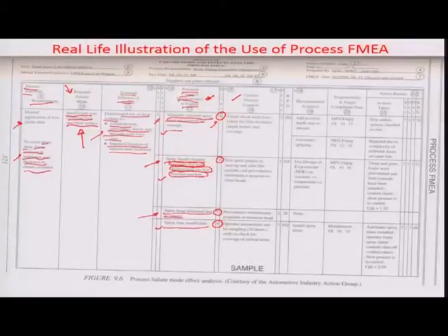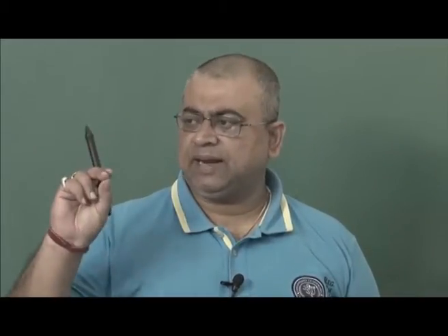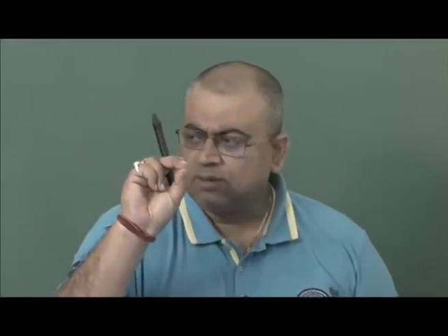For example, for the manually inserted spray head not inserted far enough mechanism of failure, he finds that the process control is to visually check each hour, maybe one vehicle per shift, for film thickness. This can be done using a depth meter, where the insertion into the wax layer might give a marking on the scale through which you could measure the thickness of the wax.